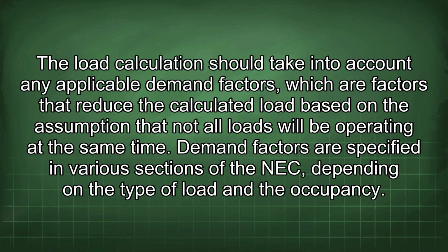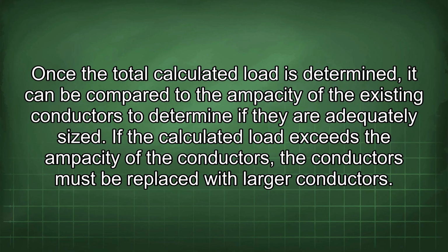The load calculation should take into account any applicable demand factors, which are factors that reduce the calculated load based on the assumption that not all loads will be operating at the same time. Demand factors are specified in various sections of the NEC depending on the type of load and the occupancy. Once the total calculated load is determined, it can be compared to the ampacity of the existing conductors to determine if they are adequately sized. If the calculated load exceeds the ampacity, the conductors must be replaced with larger conductors.